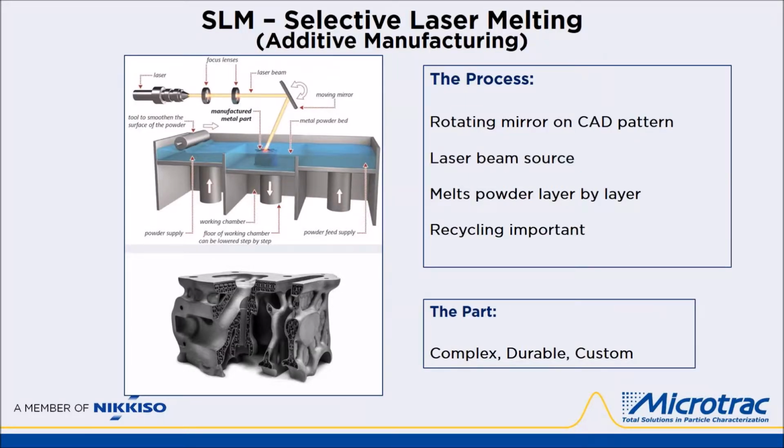Here's some more information on the selective laser melting process. The laser melting process uses a rotating mirror, which by following a CAD pattern directs a laser beam onto the top powder layer, melting the powder layer on top of the previous layer of the part. All particles not melted onto the part are scraped off while the next layer is loaded. Attempts are made to successfully reuse the unmelted powders for as many cycles as possible before it shows too much wear to meet size and shape criteria.